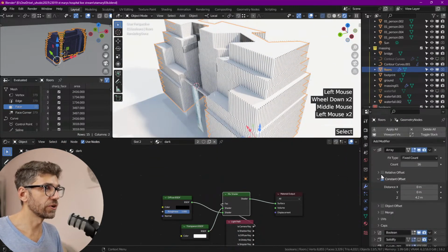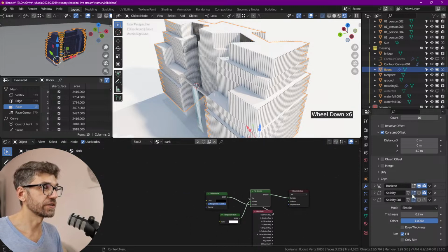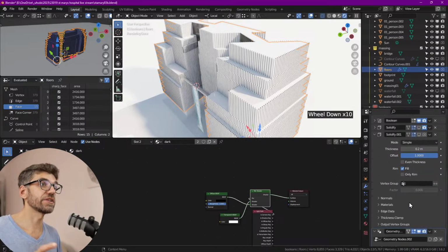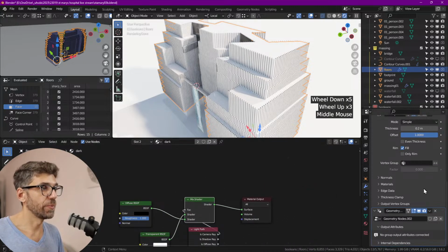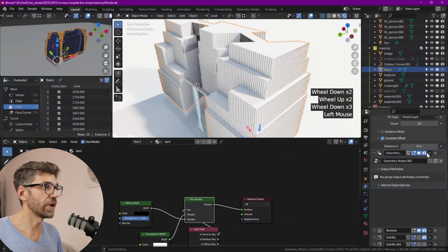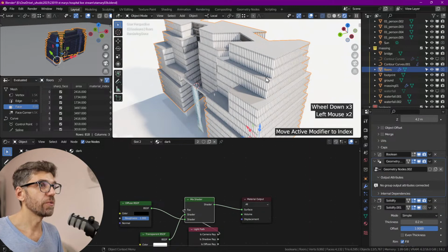The floors have gone away because we did a boolean before we had these solidify modifiers that gave it a bit of thickness, which we now don't because we needed the single faces in order to get the proper areas. So we can keep that as it is, and just move the geometry nodes around. So if we put the geometry nodes after the boolean and then we solidify, we should have those.